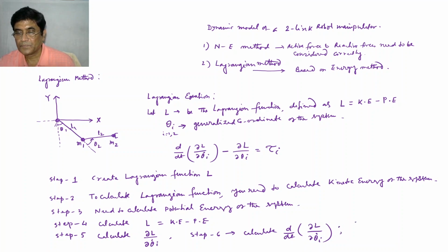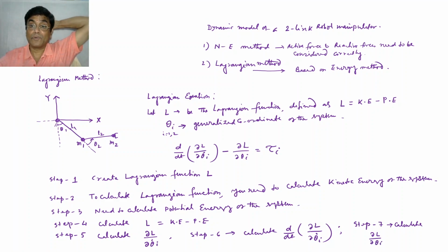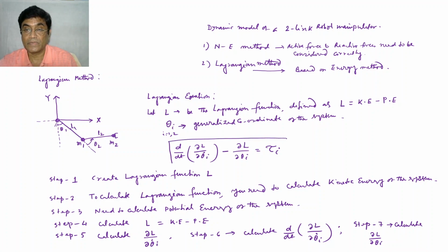Then step 7, calculate del L del theta i. So when we have all the materials, we collect them and put them in this equation and we'll be able to get the system dynamic equation. Very, very powerful.